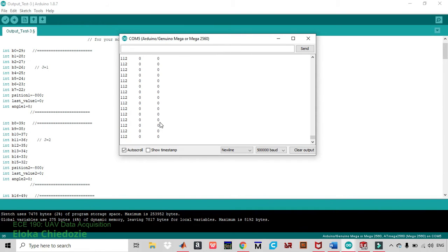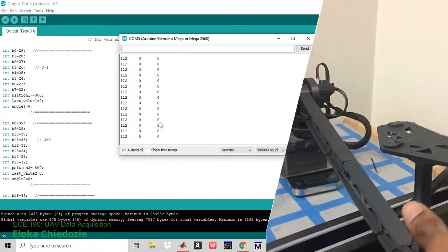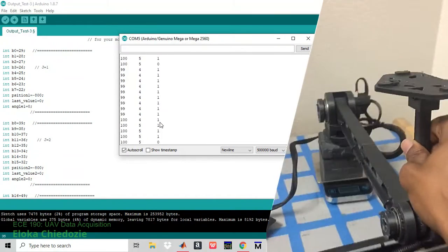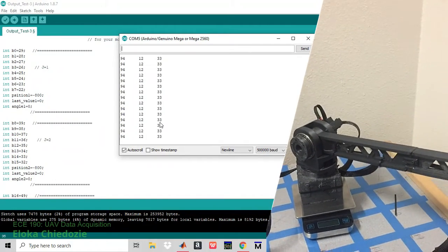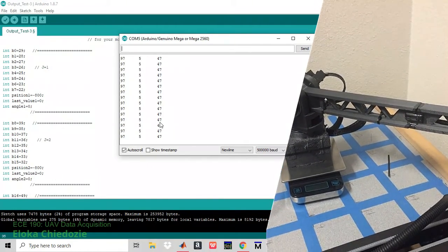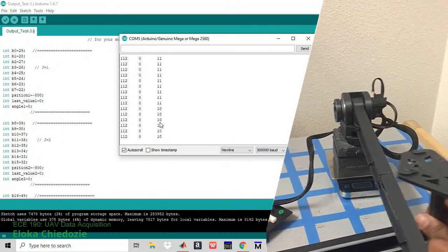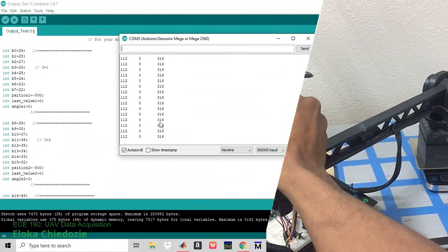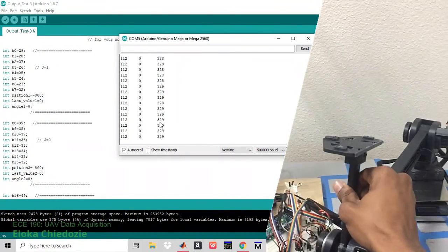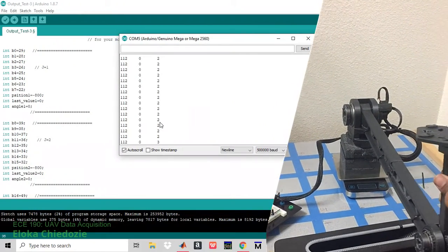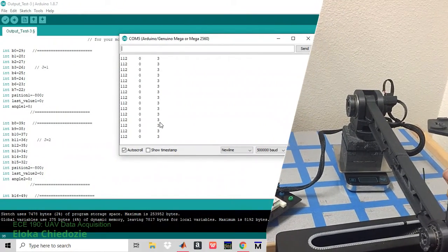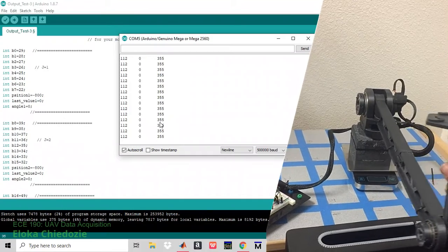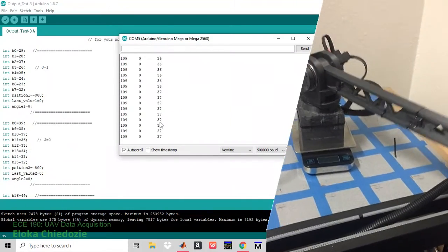So if you look at the video shown on the screen right now, you're going to see that when I move the test bed to the right, this is J1 being incremented. You see the changes in J1. If you move J1 by itself, left or right, you're going to see the resulting changes in J1, and when it crosses 0, which is the original position, it will go from 0 to 360 or 360 back to 0, and you can move.